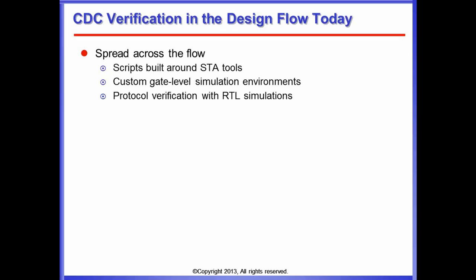They try to do this with a gate level simulation environment, moving edges to provoke the metastability and see what happens with the design. Some just have a mechanism to identify these CDCs, and then they say, okay, we do a visual check of the whole thing, and if the designer says it works, it's going to work.